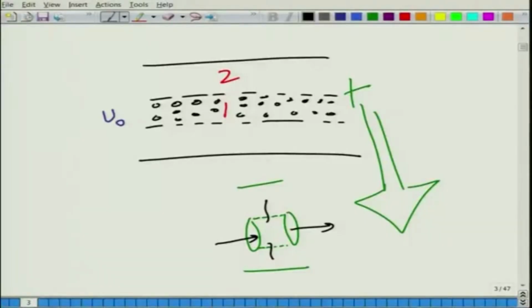In that case, for a 1D case at least, there was no flow through the cylindrical surfaces, there were only 1D flows. Okay. So, that is how we led to the derivation of the 1D equation. Now in this case of course, we have flow through the cylindrical surfaces also. So, we need to account for that. So, let us quickly write down the fluxes that one would get when such a thing is considered.